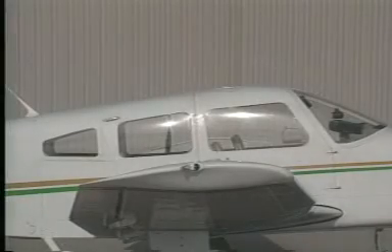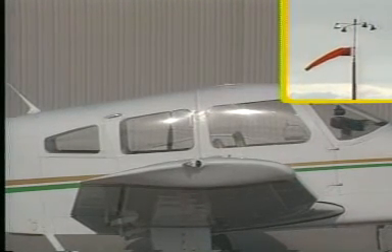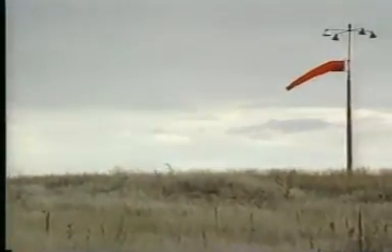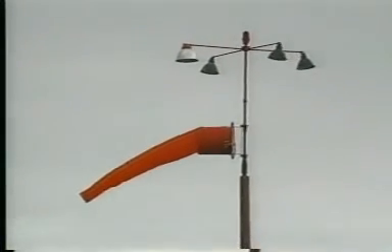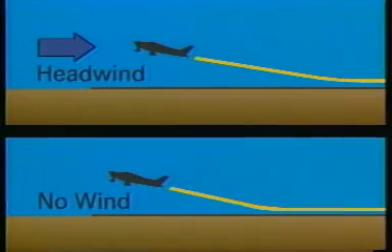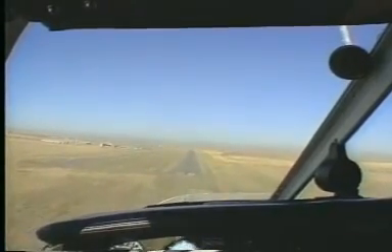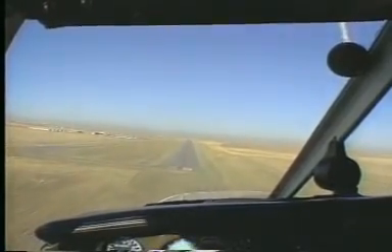You have learned that the air moving around the wings produces lift. Likewise, existing wind conditions have a big impact on airplane operations, specifically takeoff and landing performance. For example, headwinds are desirable for both takeoffs and landings. During the takeoff roll, a headwind supplies additional lift to the wings. This enables you to lift off earlier than during a no-wind condition. During a landing, the headwind reduces your ground speed as you approach the runway. This, in turn, shortens the landing roll.